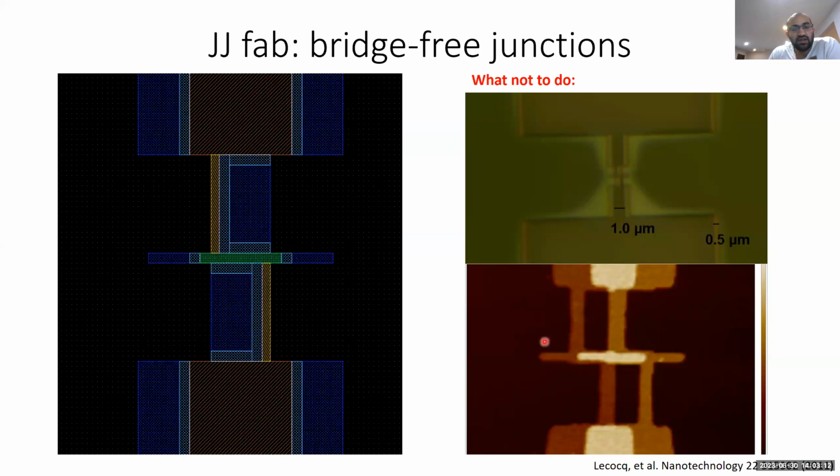Now, this is a problem that can be fixed, but it's something that you have to be aware of. And really, one way to fix it is to make this wide region a lot thinner in order to reduce the total nearby exposure to your close-by junction area. Okay,